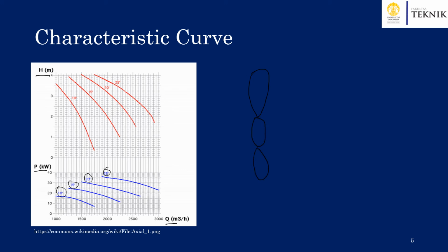It is the angle representing how the blade is twisted. The angle represents the twist of the impeller blade. It is also a common term in aerodynamics when we talk about airfoils and so on, and a common word in fluid dynamics actually. So 10 degrees, 15 degrees, 20 degrees, and 25 degrees are the pitch angles.